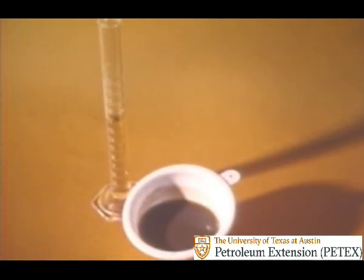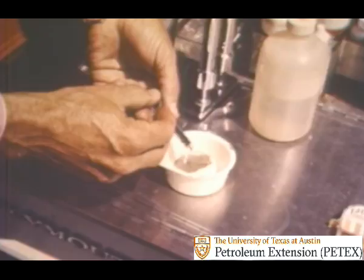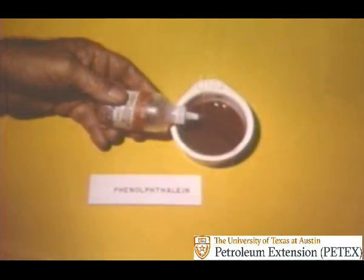Using the filtrate obtained from the test and a sample of the mud itself, several chemical tests are made. The first chemical test, especially with lime muds with a large amount of calcium, requires that 1 milliliter of mud be mixed with pure distilled water. This is used to determine what is known as the phenolphthalein endpoint. Phenolphthalein endpoint is a very accurate measure of the mud's alkalinity. Phenolphthalein is an indicator solution which, when added to the mud sample, turns the sample purple or wine-colored if the pH of the mud is above 8.3.